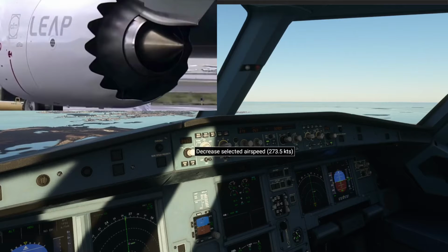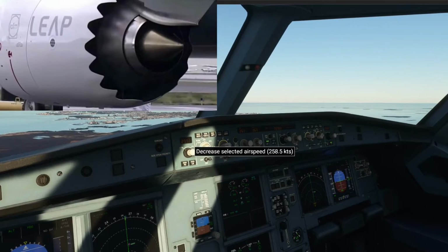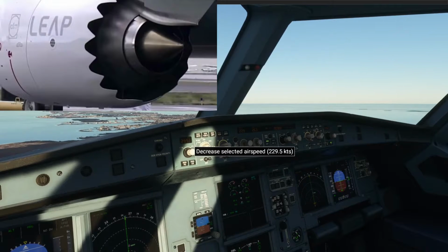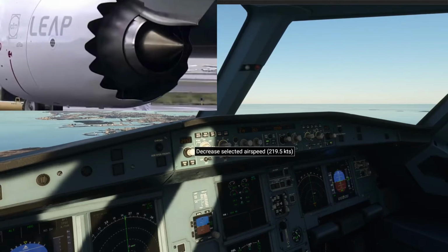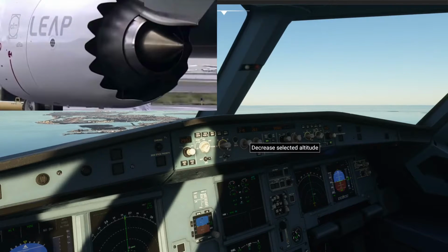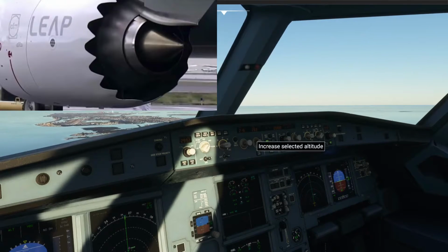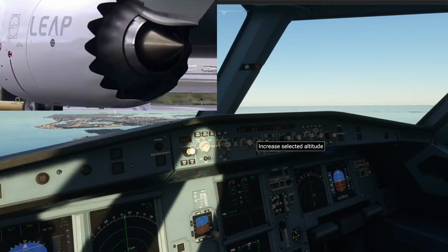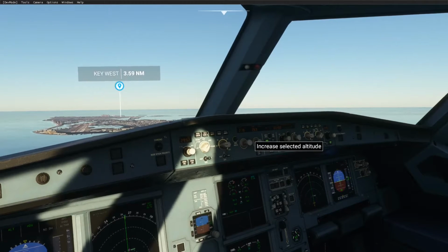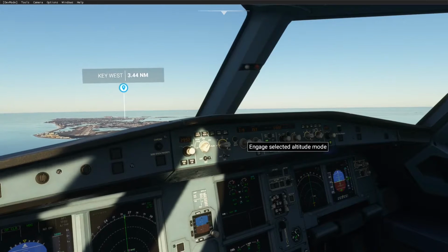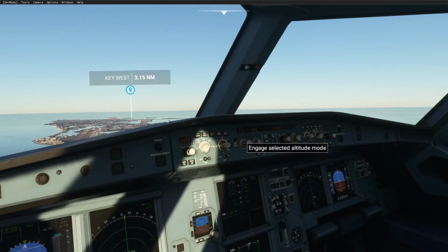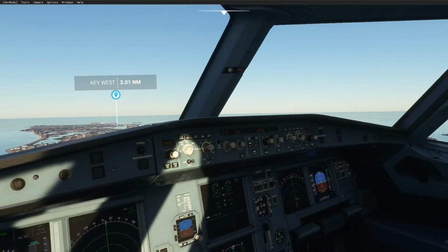So what this means is if you're having problems maintaining cabin temperature, you're going to see that in the power of your engines, probably during a taxi, and so you're going to get more powerful engines if you're having trouble maintaining cabin temperature. So it's just something worthy to think about. And also, it will do this if you're using an APU, but this time it just increases the speed of the APU, and you won't notice that, obviously, in the taxi.